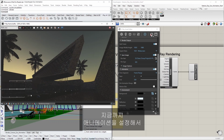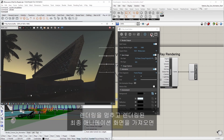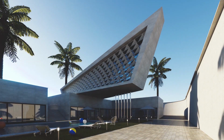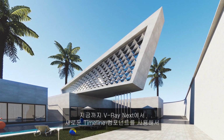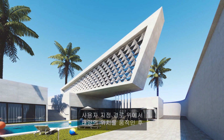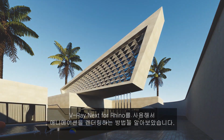Alright, now that you've seen how to set up an animation and get a render started, I'm going to stop the render and pull up what the final rendered animation looks like so you can see the end result. Okay, now you've seen how in V-Ray Next, you can use the new timeline component to animate the sun's position on a custom path and then render the animation with V-Ray Next for Rhino.